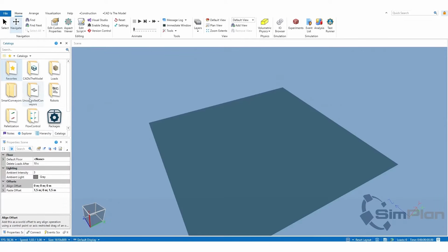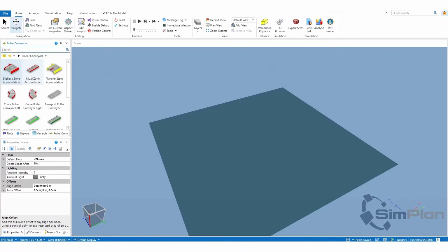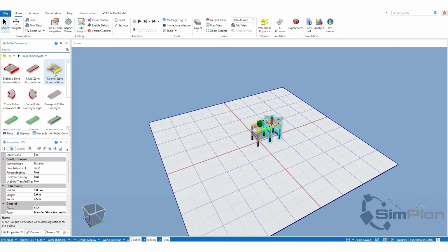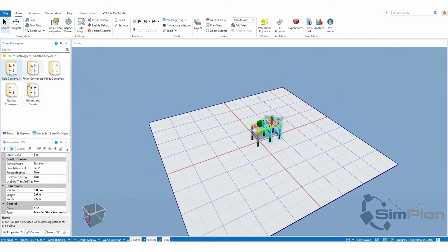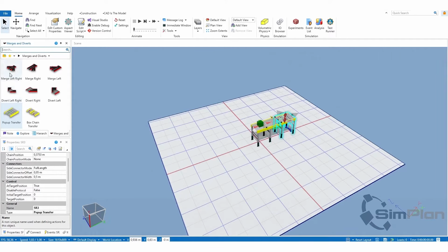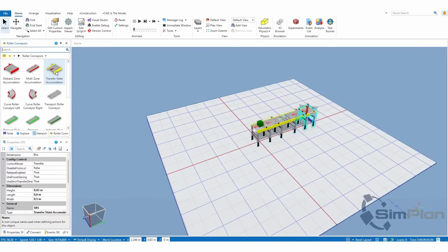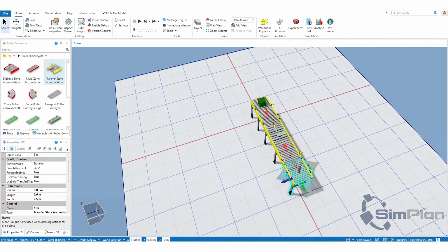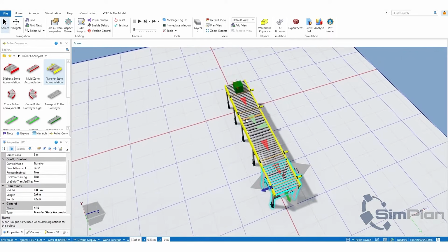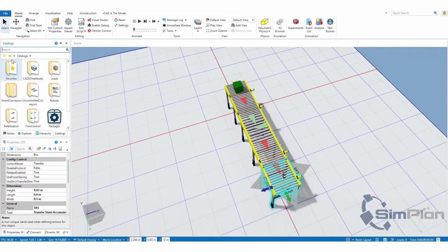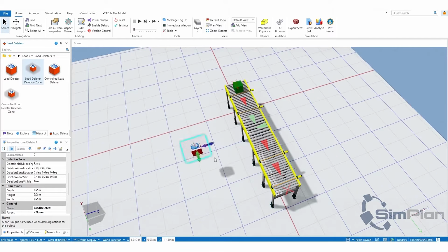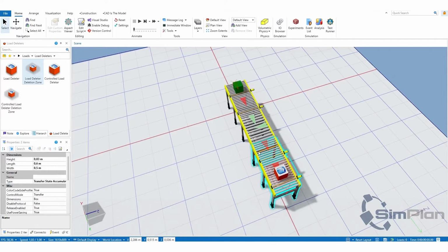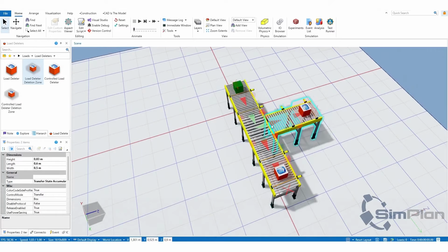Emulate3D models can be created based on 3D CAD data or the numerous standard components. This is where the standard Smart Conveyors library comes into play. The individual components are placed in the scene using drag and drop. Load creators and load deleters are used to create or delete conveyed goods and products. Snap functions support model construction and automatically take into account compatibility requirements between the components.